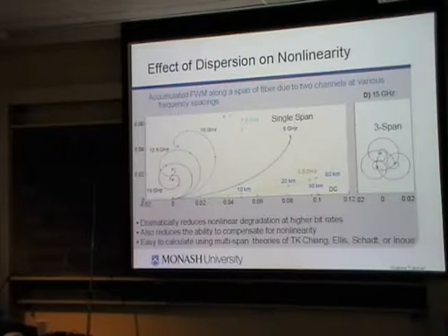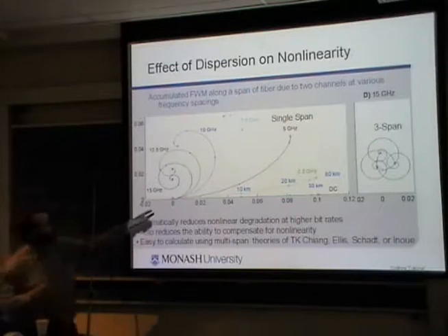So the Kerr effect, which is proportional to intensity, is strongest in the first bit of the fiber. If I divide this fiber up into short lengths and try and calculate how much nonlinearity or what these sidebands are, so I've got my sidebands being created, how big they are as I go from section to section, I plot this graph here.